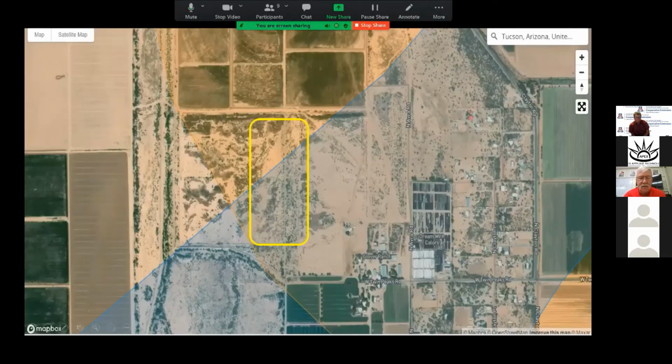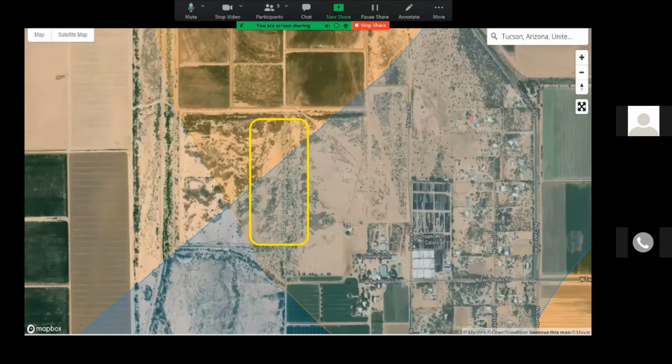And we got down into this area, we were able to actually fly the drone. And when we moved over here, the drone was operating and it would freeze and stop. And we were trying to figure out why we couldn't get it to move through its path. And we look at the monitor and it came up with the NFZ, and that means it's a no-fly zone. So we went into the drone flying app, and it showed that there were no air control areas there, it was green for us, but we were using a DJI drone, and in the DJI app, they have a note when it encounters a no-fly zone, it won't let the drone fly in there, even if you're trying to do it manually.